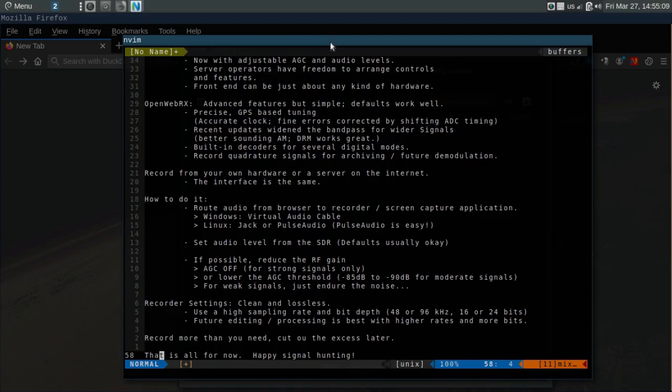And one more general tip for making recordings. Before you start tuning around, if you think there's something interesting that might happen on the radio, set your recording up beforehand, check the levels. If you can use a wider bandwidth for single sideband, widen it out some. The range 300 hertz to 3 kilohertz is pretty standard.